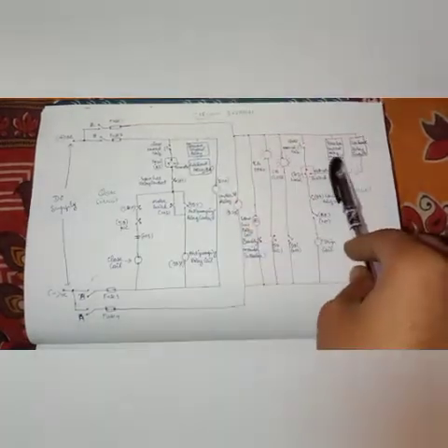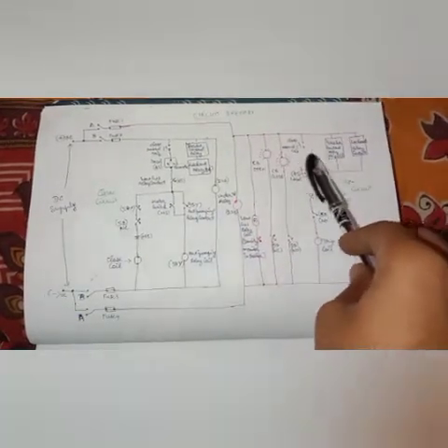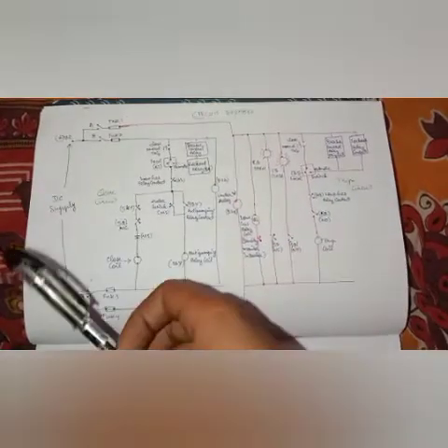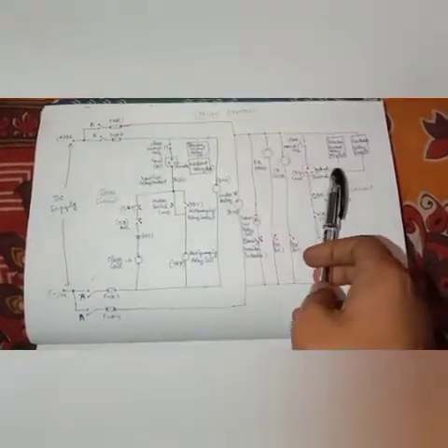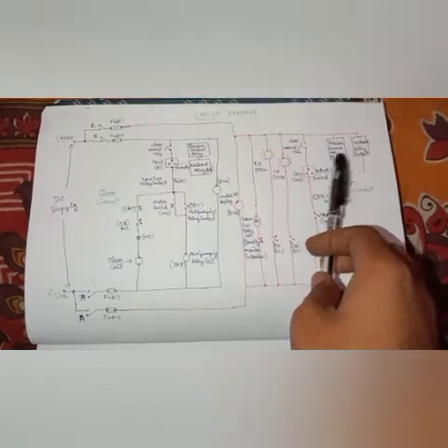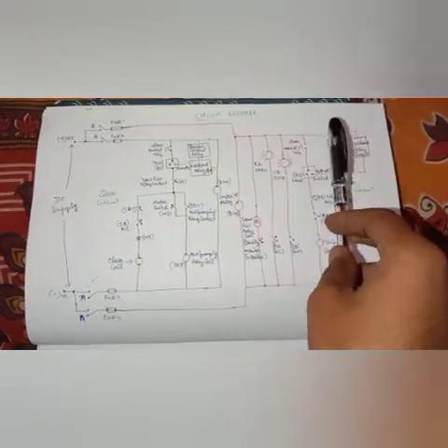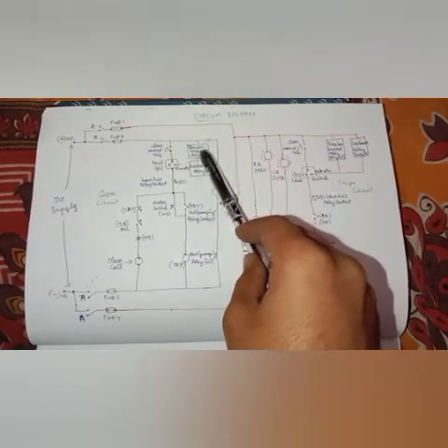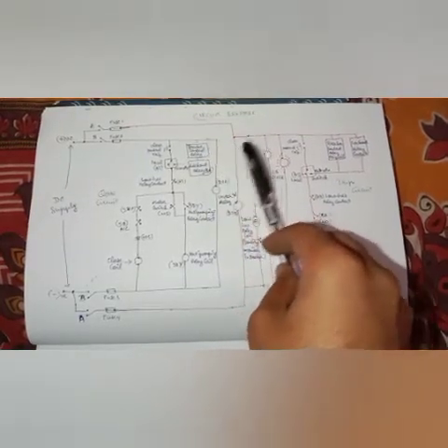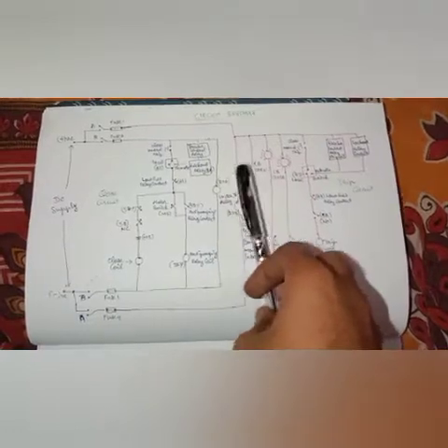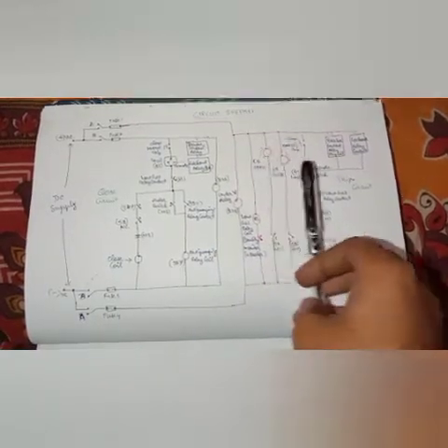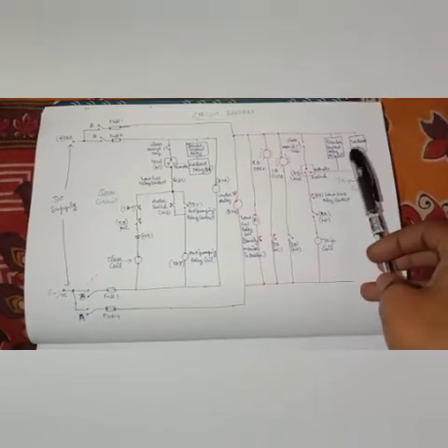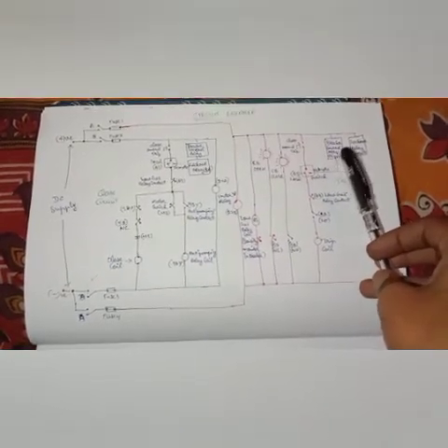In a tripping circuit they will be connected in parallel, because for trip, there may be any chance of fault. So all the tripping should be initiated. It should not be connected in a series condition, like one should get satisfied, then another one should get satisfied, and then only the tripping should be initiated. Likewise we don't need such conditions for trippings. If any fault is sensed, then directly the tripping should be initiated.